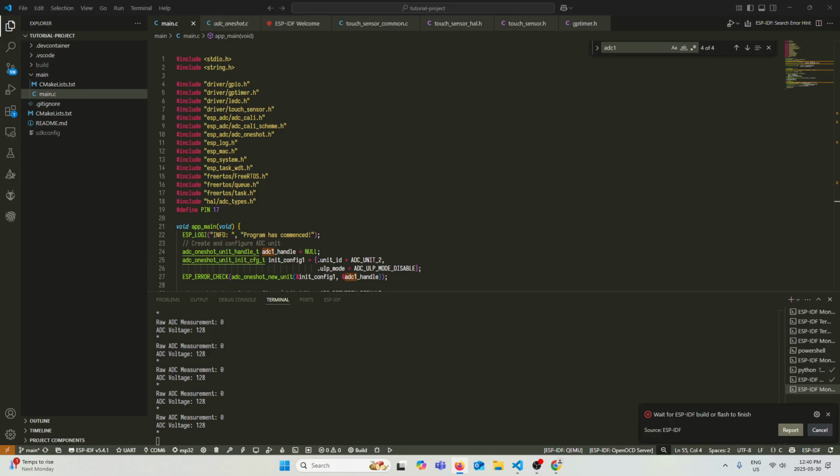If you turn it to the left, it will increase the resistance, right? So if that is the case, there will be a bigger voltage drop through the resistor. But if you change it to the other side, then this basically acts as a short circuit, because you're decreasing the resistance to a point where it's emulating the ground, right? So if it acts like a short circuit, then it'll have 0 voltage drop through the resistor. All right, great. So there you go.